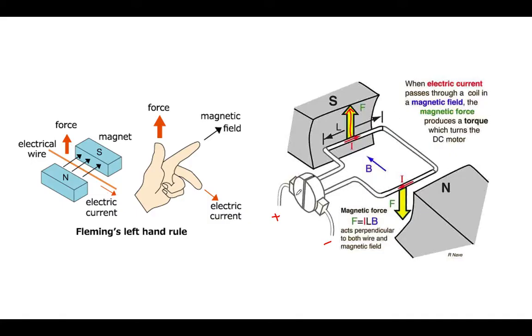So it turns, and this side copper plate comes to this side, and this side one goes there. At that time, this side arm will be here, and we again get the current flow in this direction, so it will again tend to move in the direction of the yellow arrow. It will continuously repeat every time, so until the supply is given, it constantly rotates.